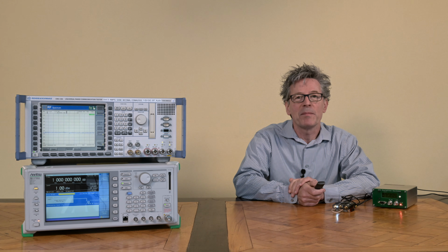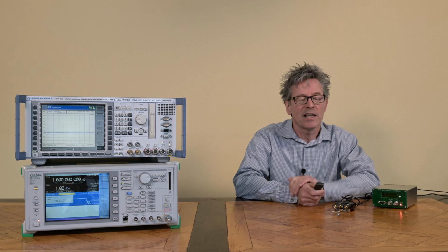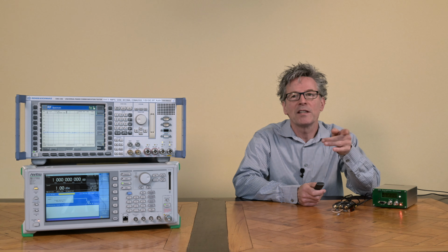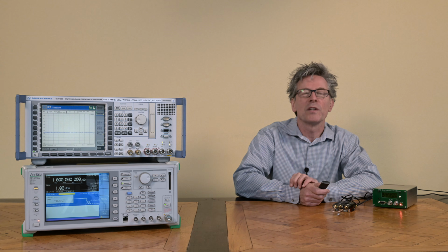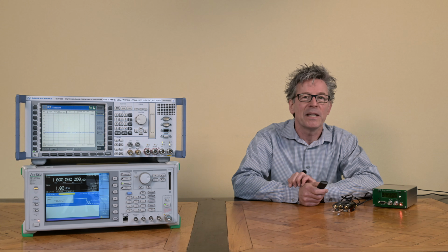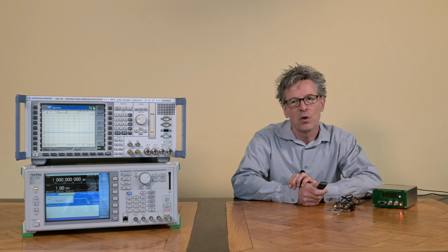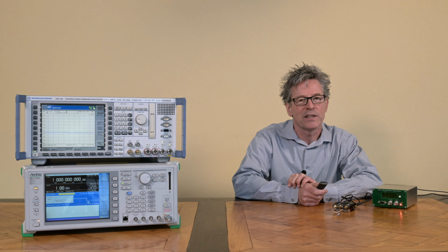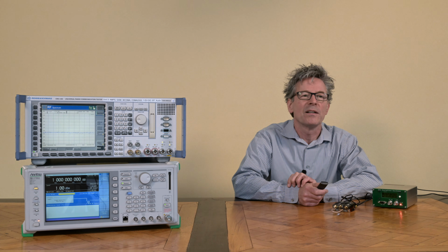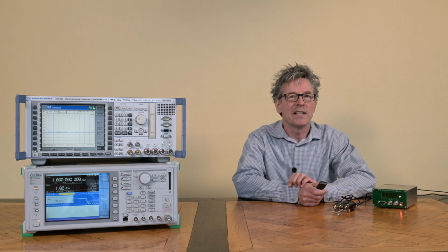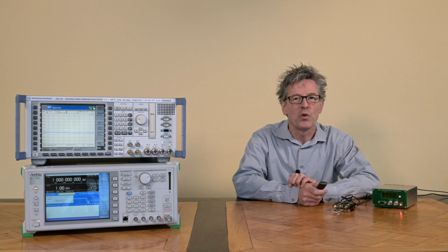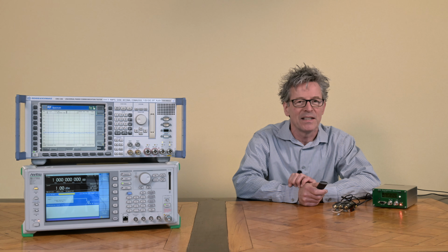With square waves, you might be interested, for example, in more time dimensions, etc. You might be interested in the rise time and fall time, like I said. It can characterize a scope, and you get all these high harmonics. And you might have instruments in which you might be interested to have that. On the other hand, the sine wave is nice and clean. It would reduce any risk, if you're concerned about radiation of all these harmonics, if you might be doing very sensitive things in the lab.